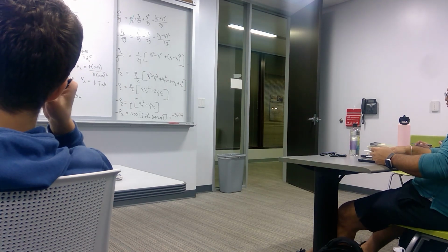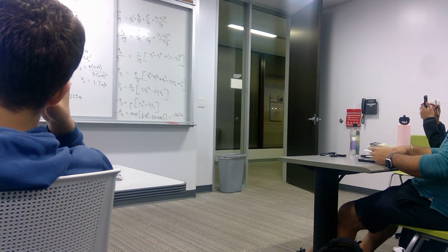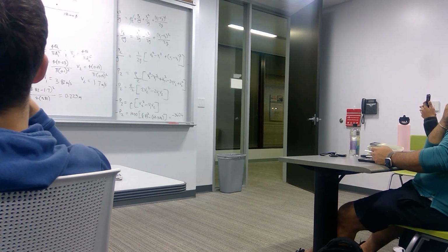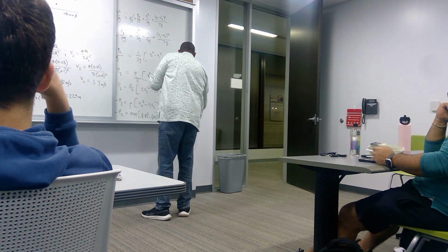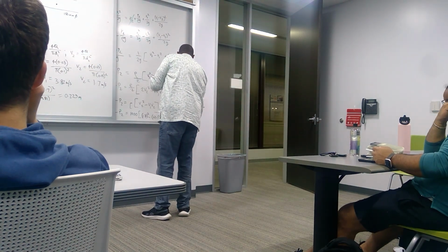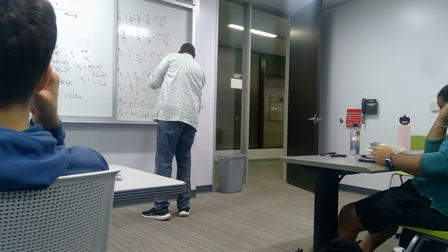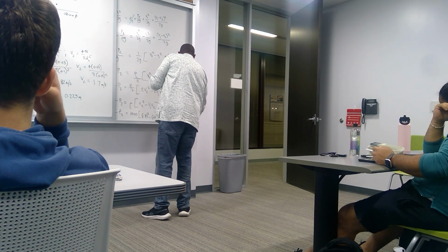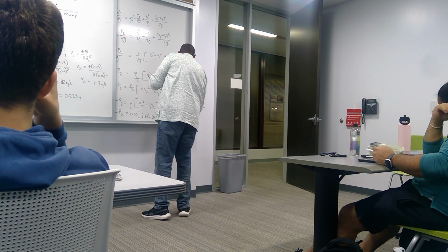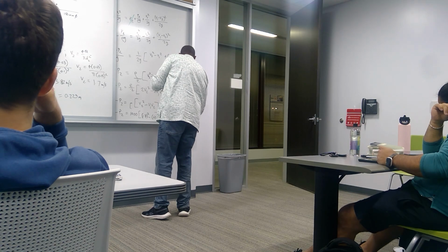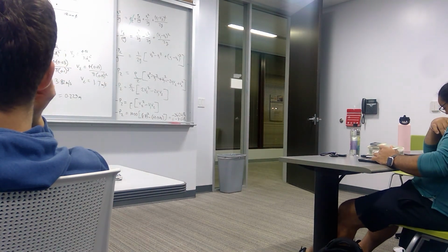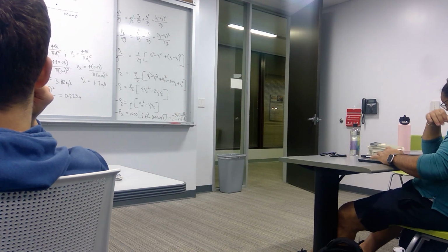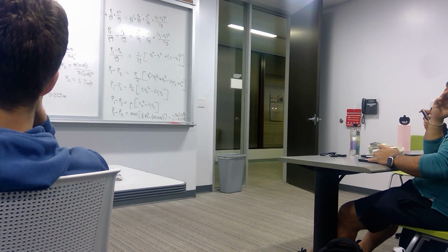It's just the other way around. And this should be Pascal, sorry, just Pascal. So it is negative 3.6 kPa, or 3.6. It's just that we have it reversed. We should have done P2 minus P1, but the answer is still the same.